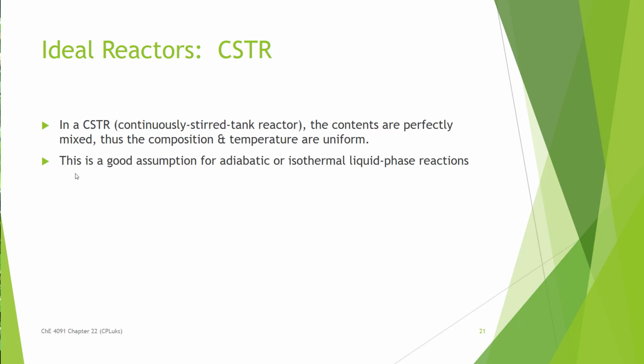So we have two types of ideal reactors, a continuously stirred tank reactor, or a CSTR, in which we assume that the contents are going to be perfectly mixed, and so the compositions and temperatures will be uniform throughout the reactor. This is actually a fairly decent assumption for the design of adiabatic or isothermal liquid phase reactions.